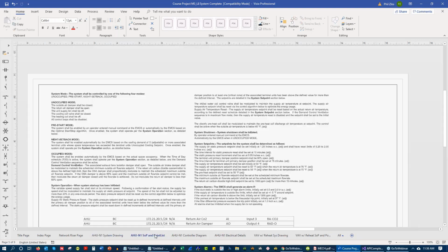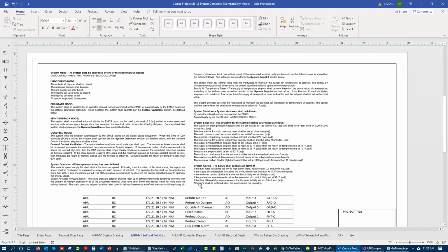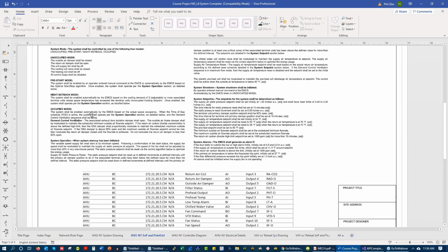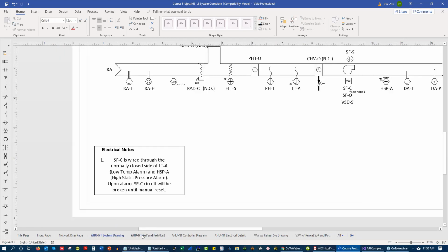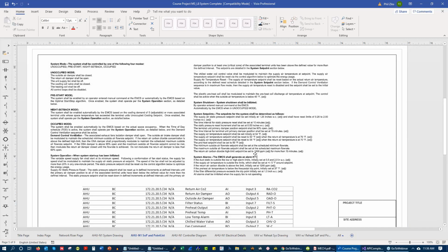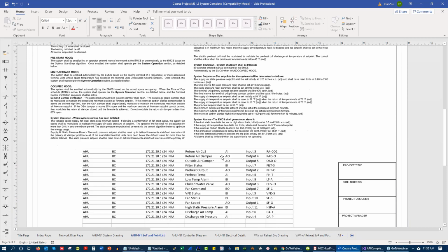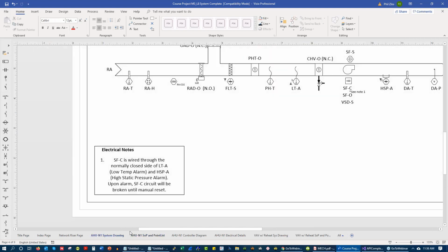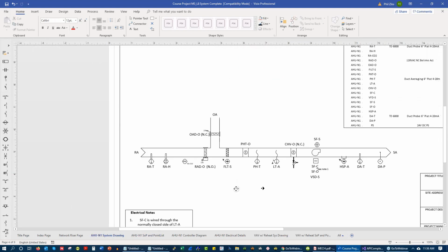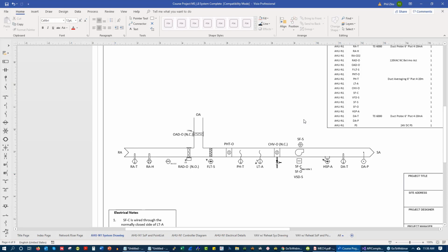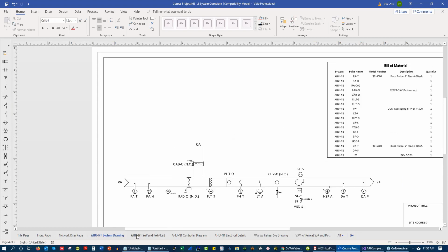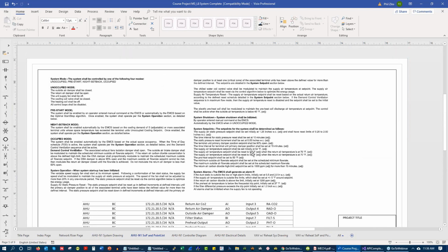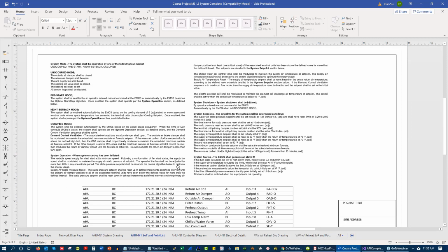Okay. And what I like to do, as I mentioned, is I like to split right here. I like to split my one line document and then my SOP onto a separate page. And the reason I like to have my SOP and points on this separate page is this is kind of my electrician, where do things go, what's my bill of material page. This is my commissioning agent functional test point-to-point check page.